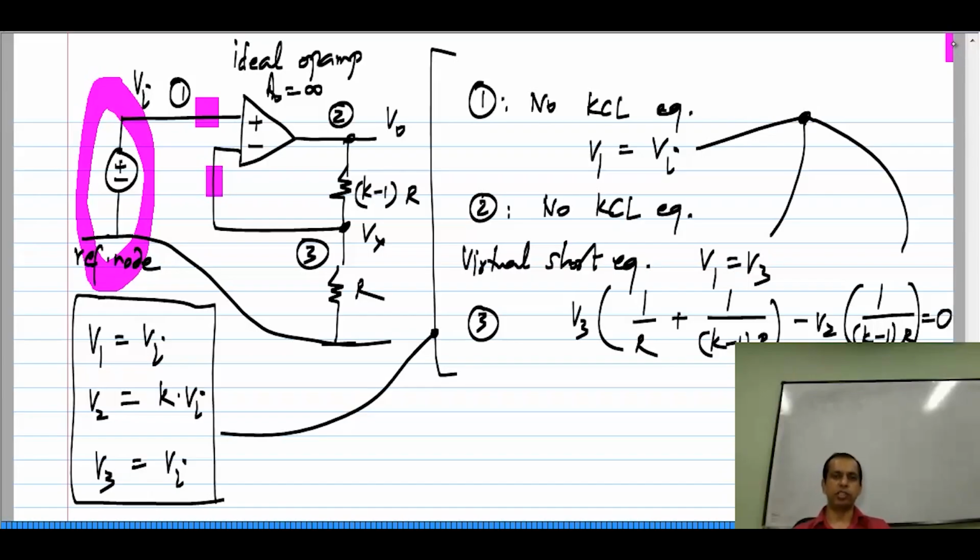If you have other voltage sources in the circuit, you have to use the supernode concept. I am assuming we will do nodal analysis, but whatever we discussed for mesh analysis also applies here. Similarly, if we have controlled voltage sources, then we again have to form supernodes and so on. Okay. So, everything else remains conventional. For the op amp, the equation at the output node is replaced by the virtual short equation at the op amp inputs. Okay.